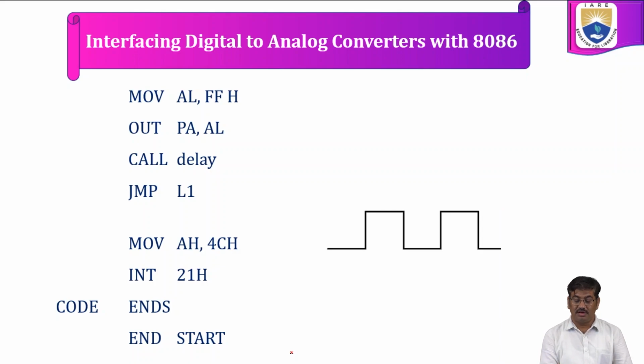If you want different delays for logic 1 and logic 0, then you can have two different delay programs, CALL DELAY1 and CALL DELAY2. If D1 is equivalent to D2, it generates a symmetric signal, where we require only one subroutine.